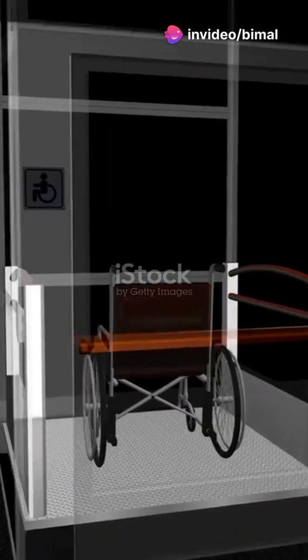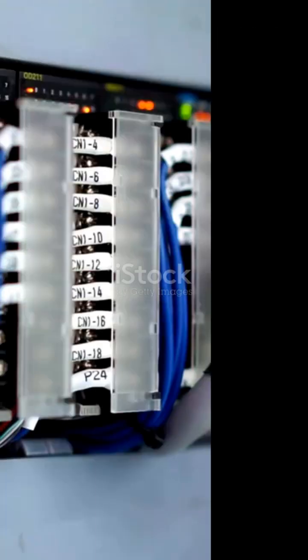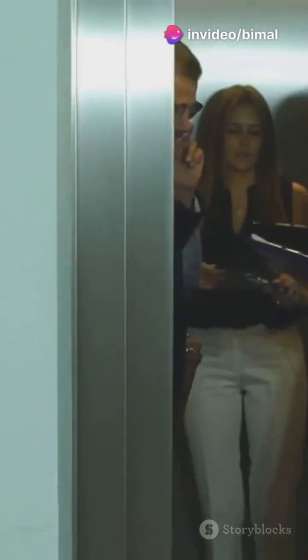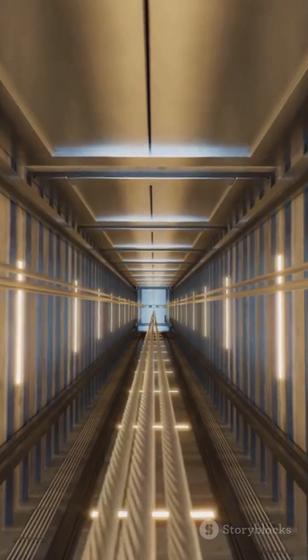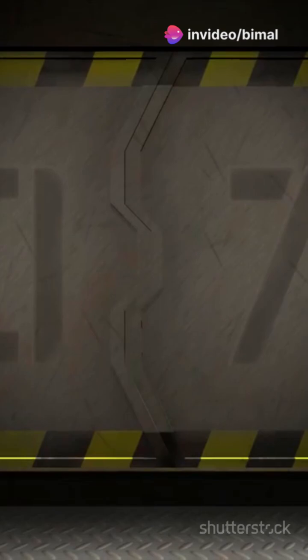Now let's delve into another vital component of the PLC-controlled elevator system: limit switches. Limit switches are crucial for detecting the position of the elevator. They send signals to the PLC to indicate the current floor position, ensuring the elevator stops at the correct floor. These tiny but mighty devices act as the eyes of the system, continuously monitoring the elevator's location. When the elevator reaches a specific floor, the limit switch sends an electronic signal to the PLC, which then processes this information to halt the motor and stop the elevator at the precise floor.